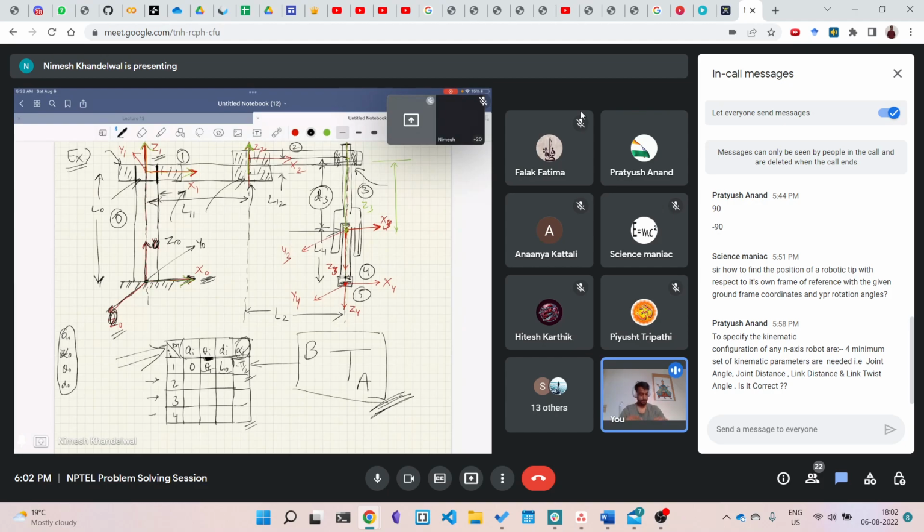I mean to say that whatever we are reading in the DH algorithm, is it for 1 degree of freedom? No, actually, you have seen that we have used these parameters here as variables: a0, alpha 0, theta 0, and d0, right? So currently, what you have learned is for 4 degree of freedom links. For a system you need to talk about the complete degrees of freedom, but this is for the general case when all of these are changing.